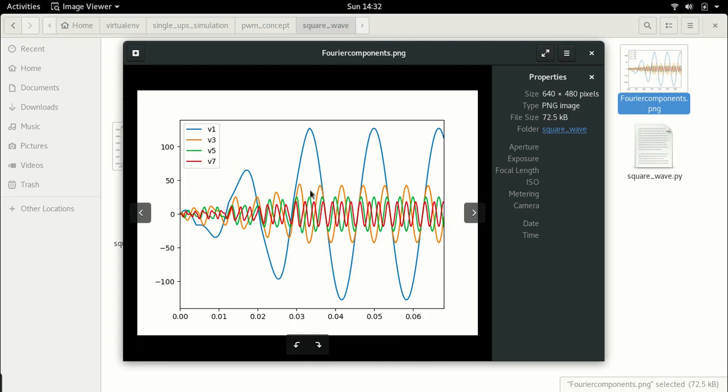But now what happens to these harmonics? We don't want this. And this is the problem with this strategy of modulation. This strategy of modulation was popular for a long time. Why? Because it doesn't take much to implement this. You can implement this with simple analog circuits. Very simple. You don't need a chip, you just need an oscillator, you need an op-amp, and you're done.